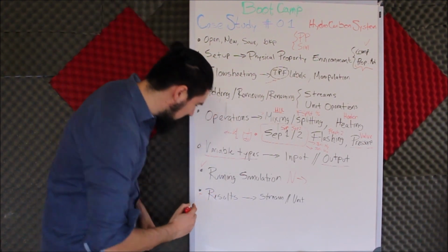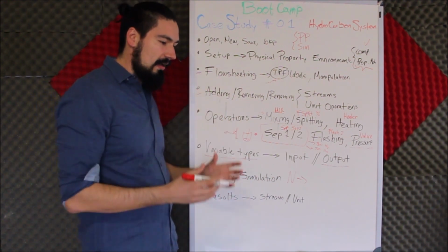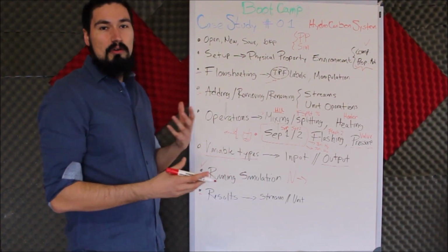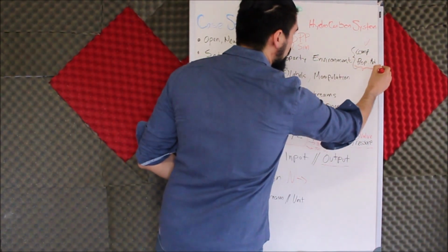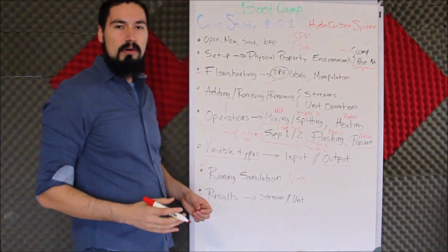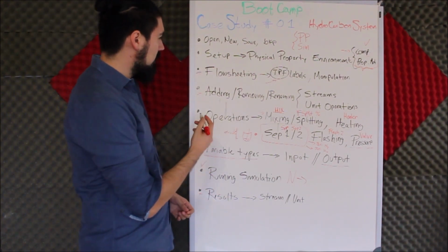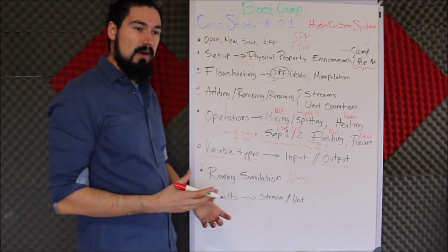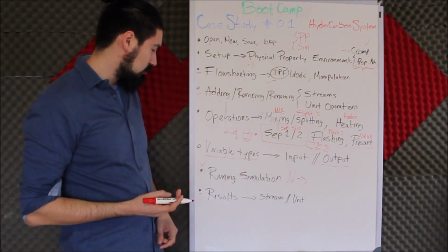And then we will see the most important part, which is of course to simulate and try to get the results, analyze them, read them, see what's happening, are we getting what we want, or maybe we don't know what's happening. This is a very important part because sometimes you have to change the property methods. Sometimes you do not add enough components to your mixture, you forgot some component. Maybe you forgot how to specify the stream, maybe you specified incorrectly, you want to change from mass to moles, or the composition was given volumetric, you will want to check that out.